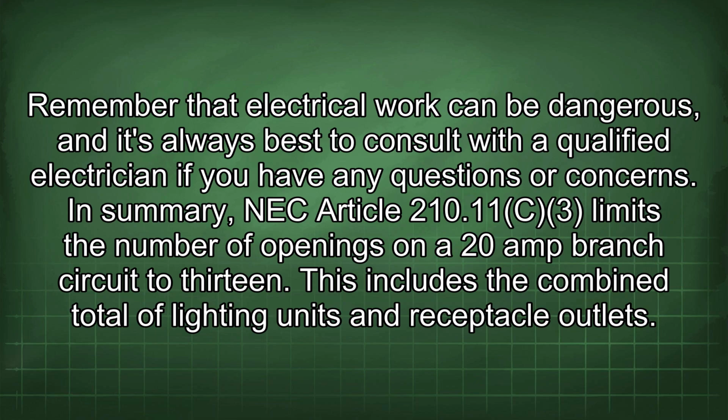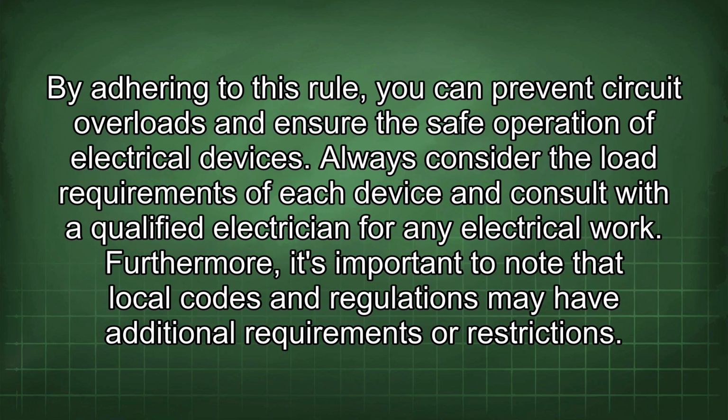In summary, NEC Article 210.11(C)(3) limits the number of openings on a 20 amp branch circuit to 13. This includes the combined total of lighting units and receptacle outlets. By adhering to this rule, you can prevent circuit overloads and ensure the safe operation of electrical devices. Always consider the load requirements of each device and consult with a qualified electrician for any electrical work.